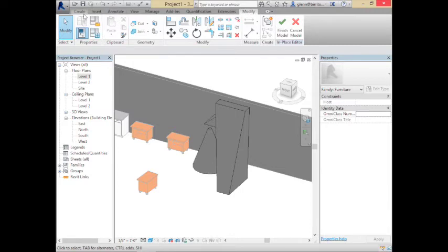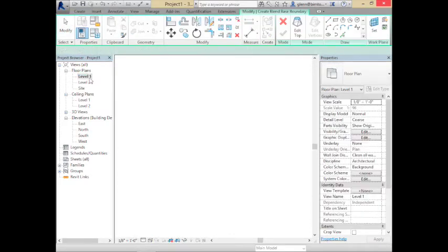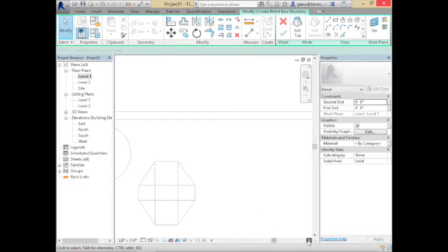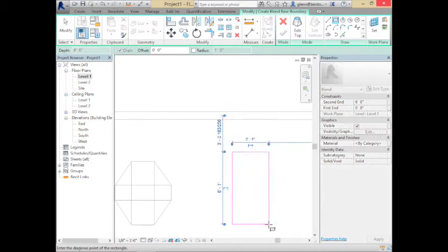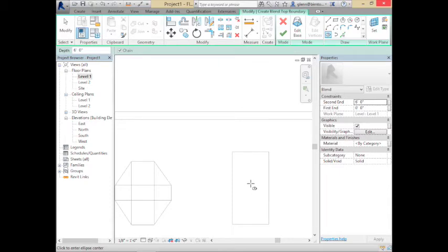Yeah, you can also blend, let me show you this. You can blend shapes that don't have the same number of sides, but sometimes it gets a little confused about that. For example, a hard one is to take, I'll do it the other way. Let me do it with the square first. It's kind of hard to do something like a square form and blend it to a perfectly round form. I'll make it really weird. Let me do this. To an ellipse. Okay, and this will give it a little trouble. At least in this blend tool, it'll have a hard time with that, because it's got 4 sides and it's going to try and make it a perfectly smooth surface. It's going to kind of freak it out a little bit.